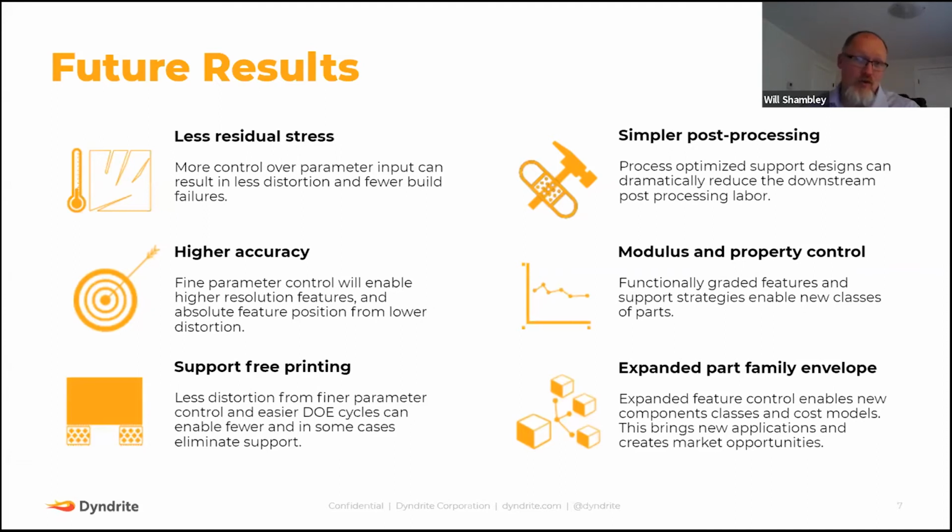I'll stick with FDM examples for now, but if you can control how big the soluble support structure points are and how thick the soluble support structure features are, and at the same time, if you can control what the other material smoothness is at different points in the wall height, you can really control your part quality and your post-processing, the ease of getting parts out.